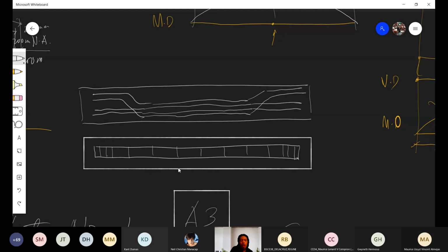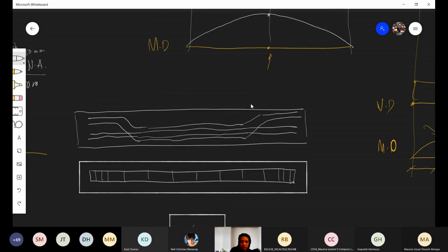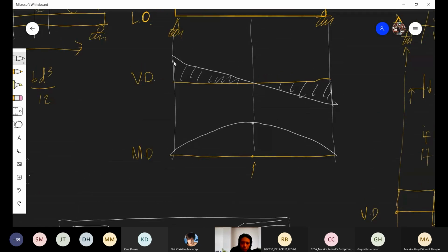If you have seen construction, the stirrups are closer together the nearer they are to the support. I'm talking about the beam. Stirrups are closer together near the support because the section near the support is more vulnerable in terms of shearing stress, since it has a larger shear force.